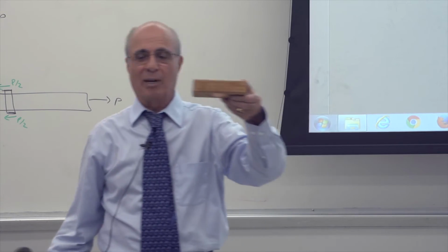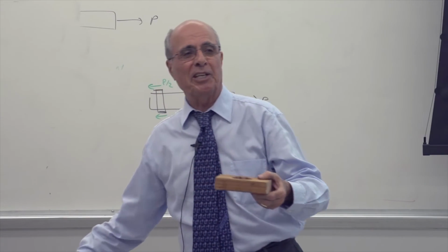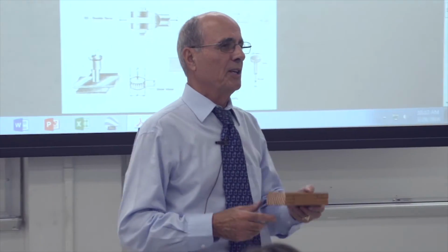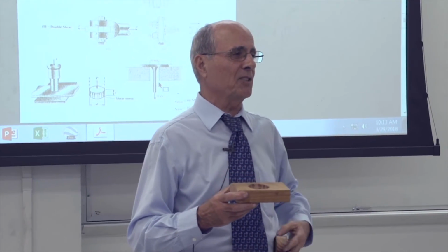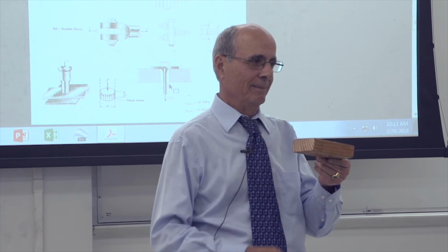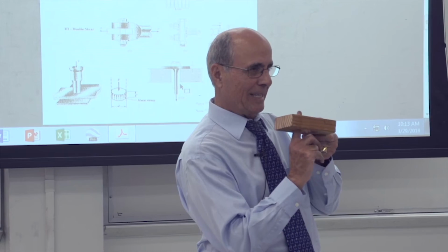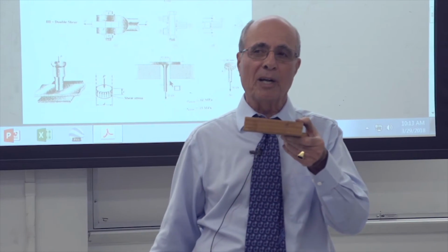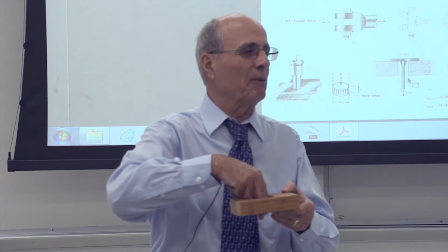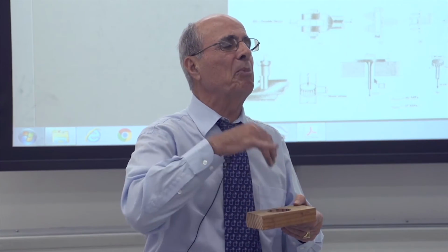Okay, this comes out. Yes? What happened here? Which material is being damaged? The steel or the wood? Wood. This is what came out. Yes? Okay. What area is being damaged? That area. Was it in the normal state of stress or shear stress? Shear. It was sheared off. Everybody see that? We call this one punching shear, please.